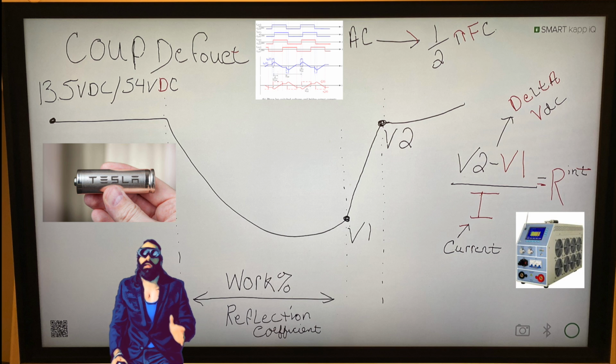There's also a secondary problem with using AC signal sources, and we'll get into this as we review harmonics and noise and switching mechanisms from the insulated gate bipolar transistors or the silicon controlled rectifiers, SCRs, 6 pulse or 12 pulse. Depending on your configuration and UPS and your efficiency of those devices, it can cause a higher level of noise. The noise floor in the DC bus can be much higher than the signal source of an impedance or conductance-based meter.